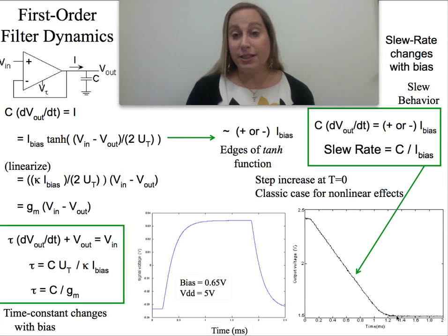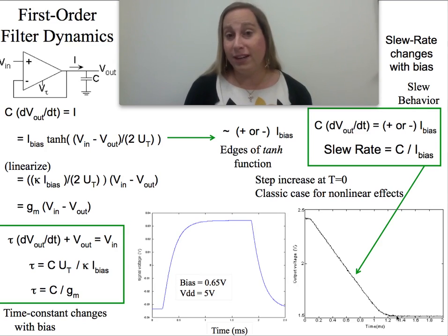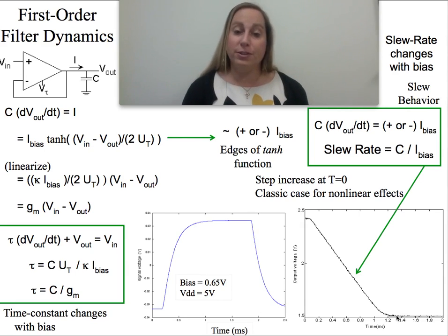So you'll constantly see things in terms of slew rate being one way to characterize the nonlinearity. It's not the only way nonlinearity shows up, but this is one for a particular function, particularly seen when you use tangent type functions. But it's important to kind of see the entire structure, because you might say, oh, I never want to have slew rate effects. Well, what if I have a circuit where I really want to have something that changes linearly versus time? Maybe I do. It'll all depend on what you're trying to build and what the resources are that you have available to build it.